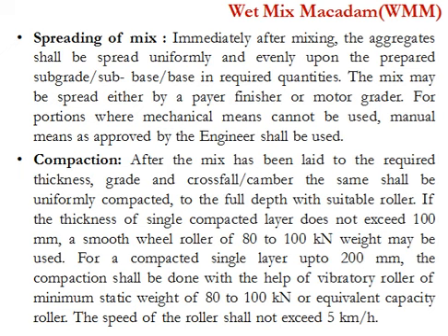The first layer will be laid by motor grader, and the second layer of the mix shall be spread by a WMM paver finisher capable of paving a minimum of 4.5 meter to 9 meter width, and the layer may be tested by depth block during the construction, and no segregation of materials is allowed.